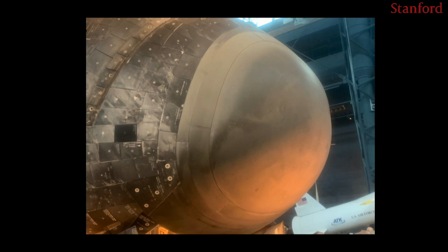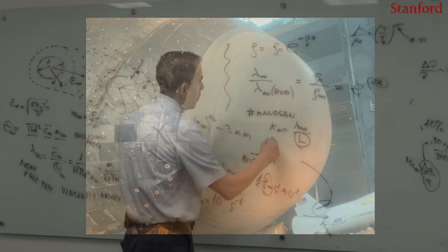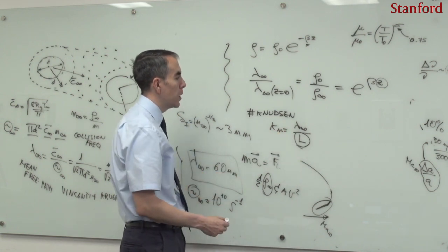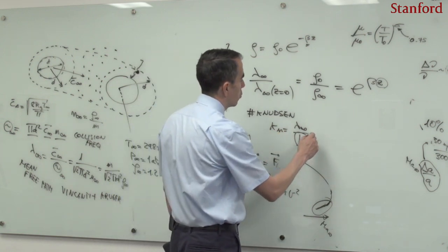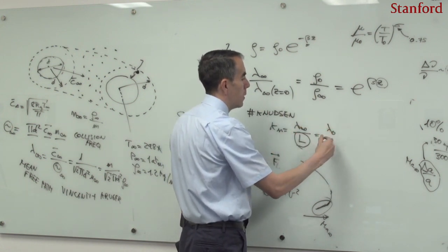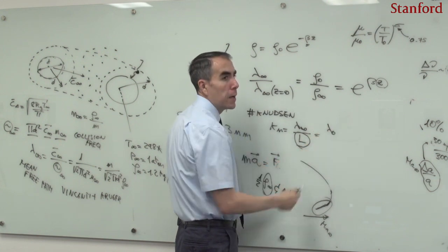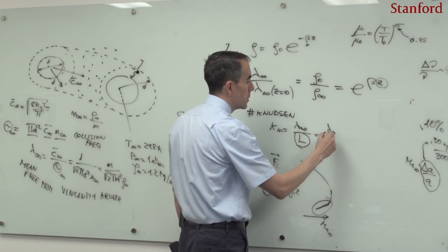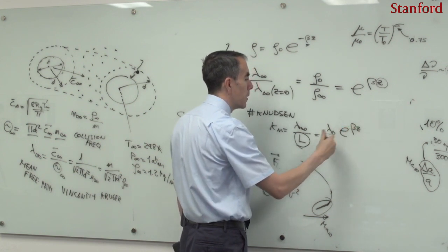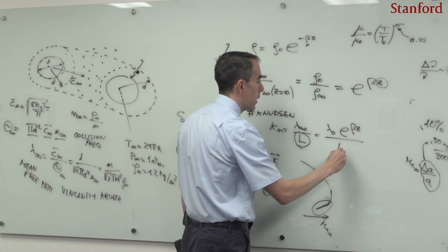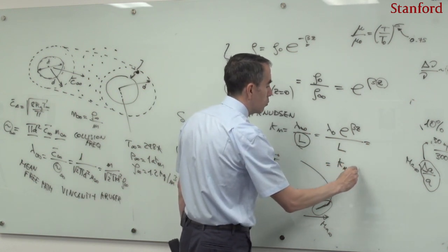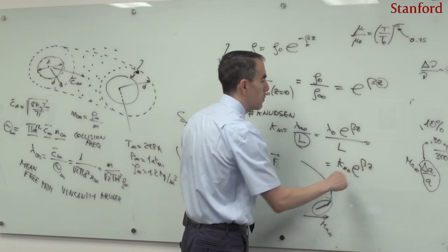So taking that 1.2 meters, right, one wonders, at what altitude do I get a Knudsen number that is equal to 1? Well, the only thing that one needs to do here is to, again, substitute this relation there. So this will give me lambda 0, let's say lambda at the sea level, multiplied by the exponential of beta multiplied by z and divided by L, right? So this will give me just a Knudsen number at sea level multiplied by the exponential of beta multiplied by z.